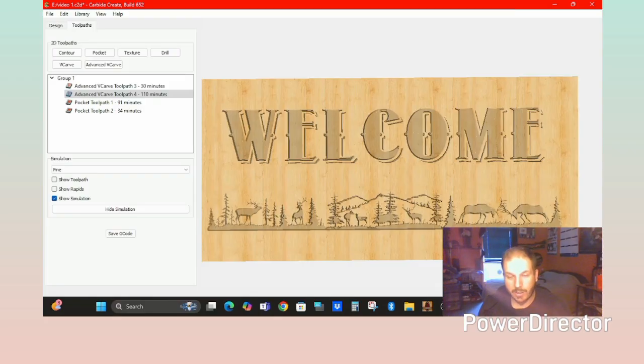That's the thing about the Carbide. If you get it, it comes fairly simple. You get Carbide Create, you get Carbide Motion on your computer. When you open Carbide Motion, you plug in your CNC. It asks you what is your machine, if it's a 4 or 5, whatever.